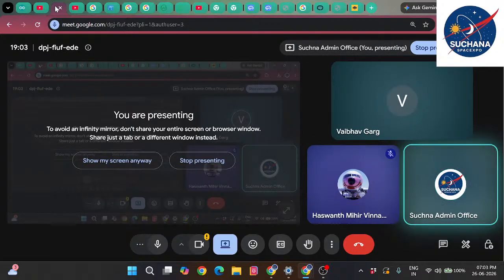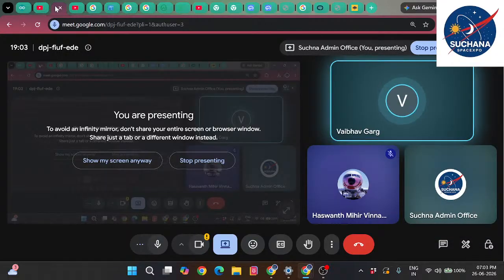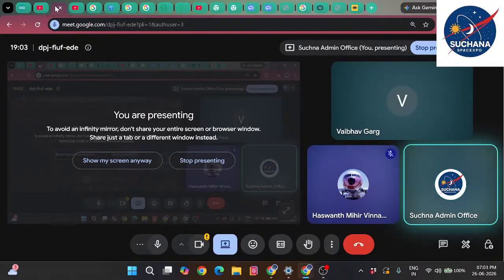If I am placing a motor driver, I want to make a circuit board in which I have to place a motor driver and a microcontroller. For that I use male header pins. So how do I make those male header pins? Those header pins are also available in LCSC. Just search for header pins, copy that part number, and place it in the layout. You will get header pins. That's it.